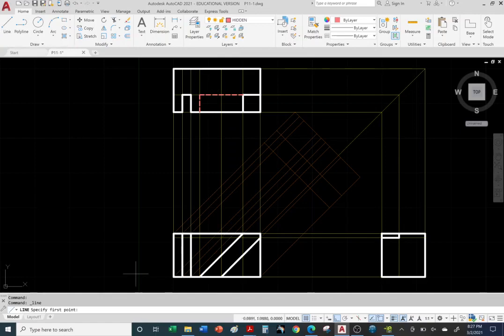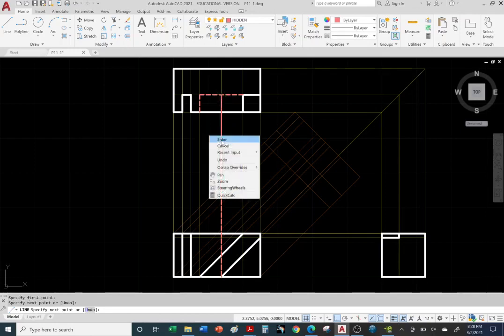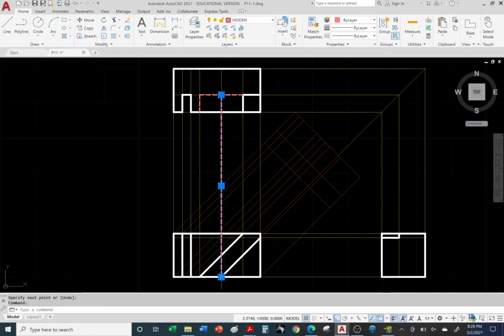Okay, once again, go to line command, and here's the other vertex. So this is the opening once again, the exit at the bottom for this angled rectangular groove. So let's go to this vertex and go straight up. And there it is. There's the opening. Click, right click, enter. And let's go ahead and shorten it. And hit escape, and there it is. Okay, so if you slide down, you'll slide down, and this is the exit. Okay, so that's it for the top view.